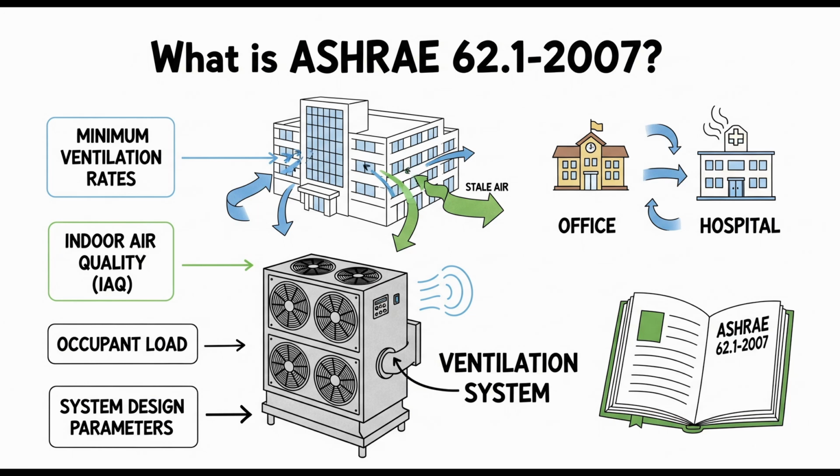Like in the U.S., the EPA's NAAQS for pollutants like particulate matter, PM10, PM2.5, ozone, stuff like that. Table 4.1 lists them. So basically, are you building somewhere that already has known air quality issues? Right. But that's not all. You also have to do a local observational survey right around the building site. Like boots on the ground? Yeah, exactly. Appendix H even gives a template.